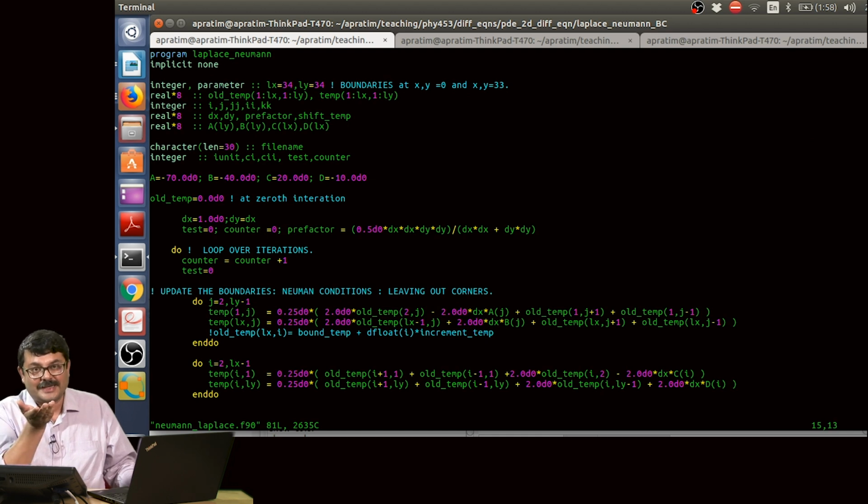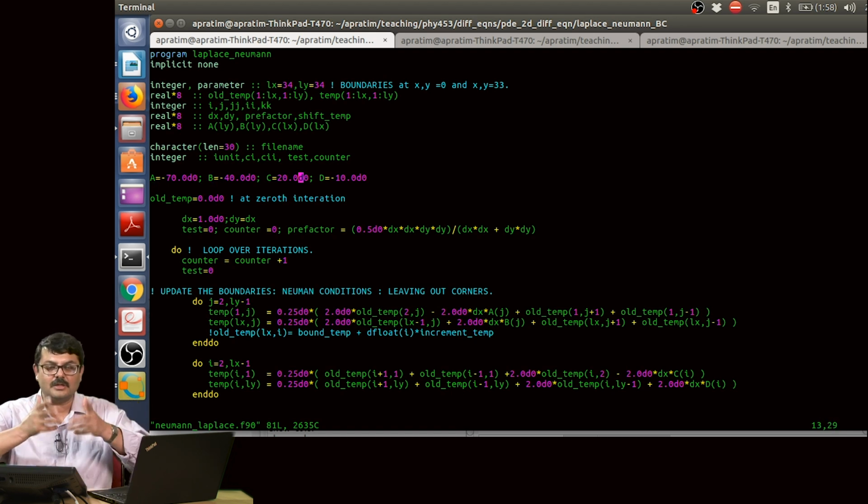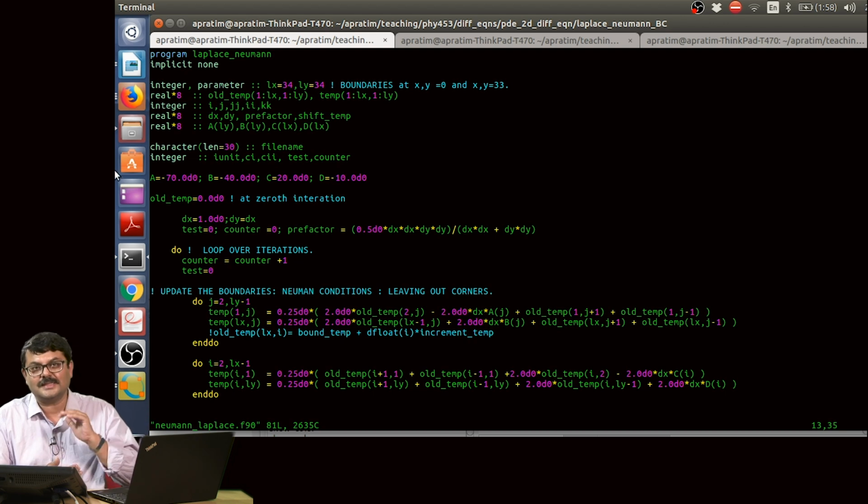And if you are talking in Kelvin, setting the temperature arbitrarily, the initial condition if you like, to 0 is pretty arbitrary, and from that all that you have is the amount of heat going in and the amount of heat going out. So, all that it cares about is the gradient in temperature, the changes in temperature about this certain arbitrary value of initial temperature scale that you have set.